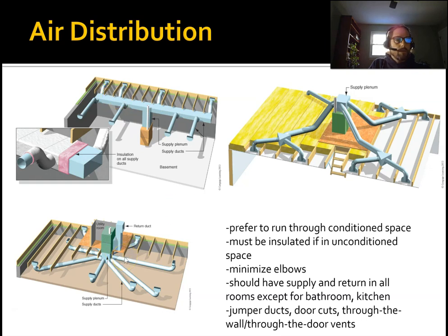You can also have this, which is called a spider duct, and this is called radial. So the only real difference here is, see, the spider duct, you have, again, a supply plenum, and you have these trunk lines. So you can see this comes out to these little mixing boxes that then have these smaller ducts. Okay, that's the spider part. It kind of spiders out. Whereas your radial is just a central supply plenum. It could be in the top, it could be in the bottom, but there's still a supply, and these are singular ducts that go out to the spaces, whereas the other has these secondary ducts. That's what differentiates the spider duct system from the radial.